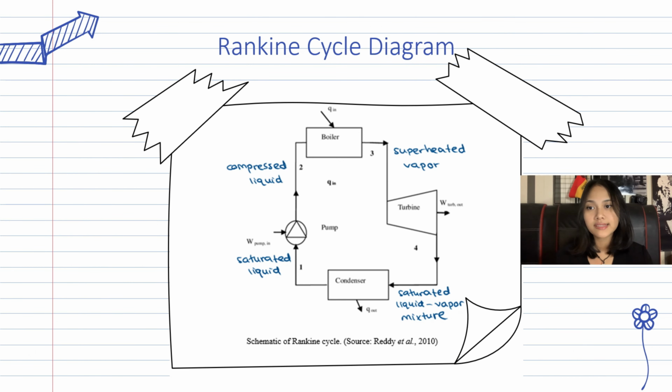The computation starts with the Rankine cycle that employs water as the working fluid to produce the electrical power. The Rankine cycle will undergo 4 processes, starting with process 1 to 2. Superheated vapor enters the turbine where isentropic expansion takes place, and then the work is produced as the shaft connected to the electric generator rotates. There will be a pressure drop and temperature drop of the steam before entering the condenser.